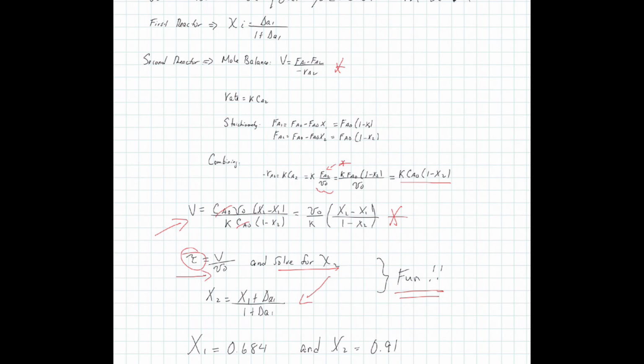If I calculate the Damköhler number and substitute in this equation, I can see that for x1, which is this expression that we used, and for x2, these are the corresponding conversions for this system. And it is very clear to see the effect of having one single reactor, or having parallel reactors, or now having a series of reactors that are CSTR.